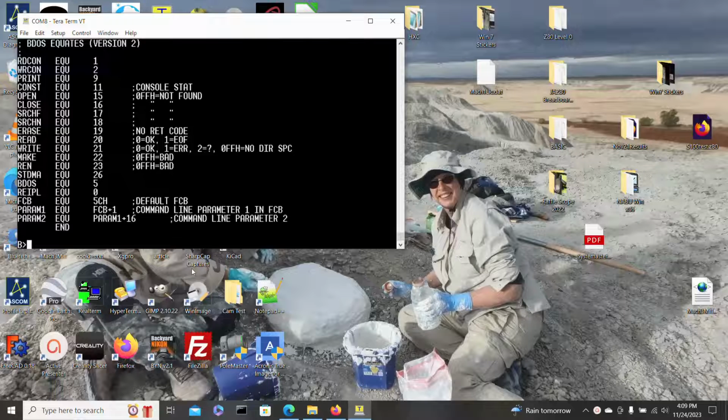This transferring over the serial port like this, basically you're expected to send text, and it doesn't handle the non-printable characters correctly. And if you're sending an executable file, it could have any of the 256 characters in any particular byte, and they're just not going to be handled properly, and it doesn't work. So you've got to send the file as text over to the micro decision and use the assembler over there.